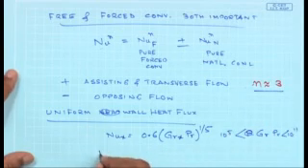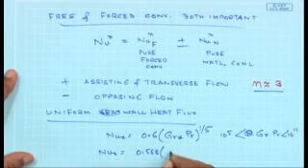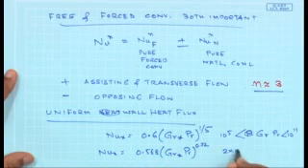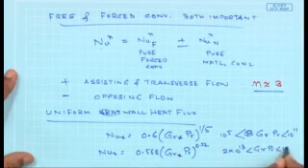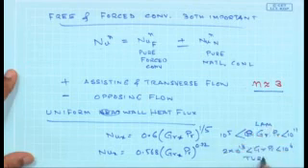And for the case of turbulent flow, this is going to be 0.568 Grashof number times Prandtl number to the power 0.22, where it's 2 into 10 to the power 13 < Grashof number Prandtl number < 10 to the power 16. So this is for laminar, this is for turbulent.